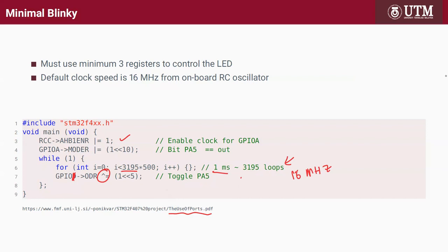So this LED will blink at 1 hertz, because it is high for 500 milliseconds, then I toggle after that. So it will be 500 milliseconds, I think. Theory is there. The exact number is to be tested by you guys. Since you are doing your assignment, you can check it out for me. If not, blame whoever made the notes. But it should work.